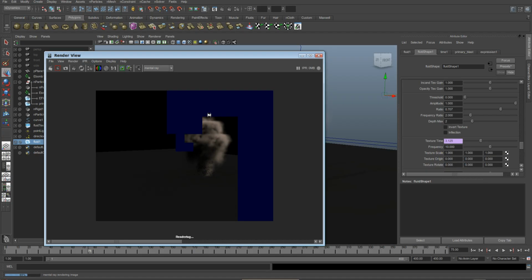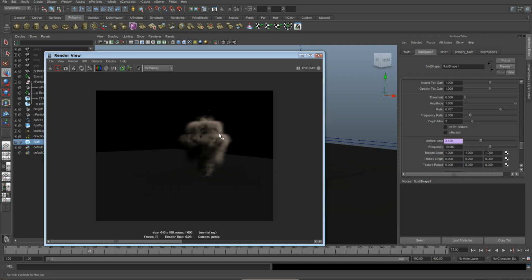So we get a much more smoke-like feel already. And again, there are ways that this is not so good, where it's plateauing out. This is because the density is whooshing the fluid off the floor. There's no turbulence, there's no velocity swirl, there's nothing here yet to mix this up, which we will look at adding in the next part.